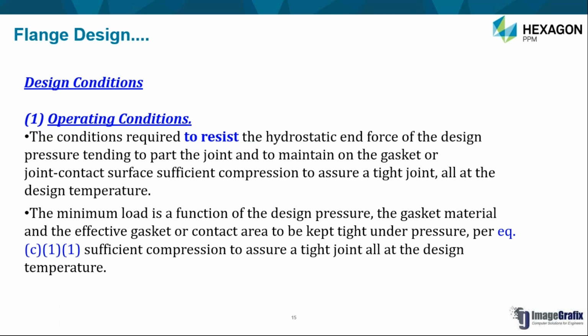As today's agenda is dedicated to understanding the procedure of the design of a flange as a non-standard flange with reference to Appendix 2, where the actual pressure and actual temperature will be faced by the flange, the flange should have enough strength to withstand the stresses generated because of the applied pressure, and it should also have enough rigidity so that it does not have any kind of deformation from where the leakage can start. So basically the primary function of the flange is to serve for this purpose as an operating condition.